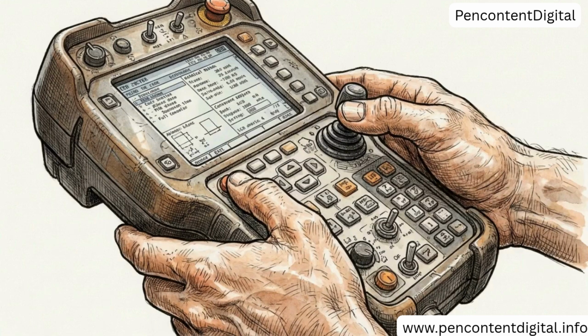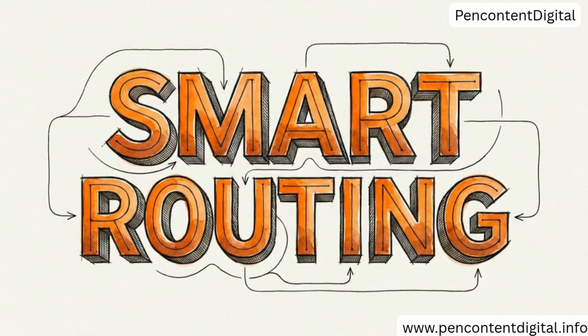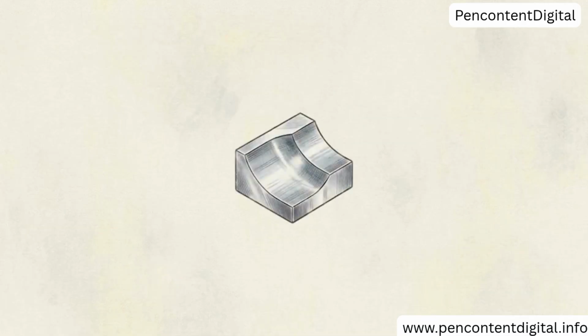Manually teaching a robot to trace a complex curve by jogging it from point to point is slow and prone to human error. Automated path generation resolves this. Rather than guessing coordinates, RoboDK extracts toolpaths directly from the geometric data of the CAD file. A continuous path is mapped perfectly along a complex curved edge or surface.